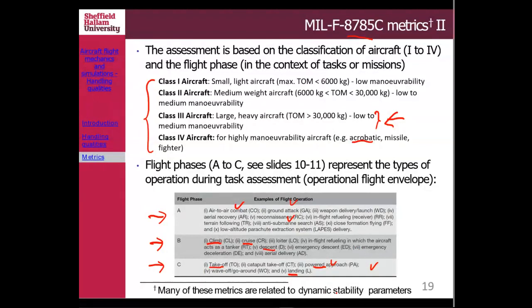If you have good sensitivity at low speed, hopefully at high speed it will cover that altogether. So that's why you could assess the handling qualities of your aircraft in flight phase C.